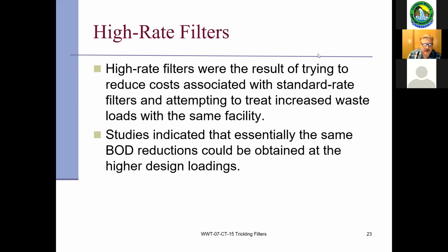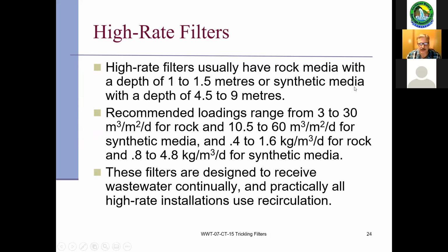So high rate filters, we talked quite a bit about those already. I just want to make mention that the media with rock is 1 to 1.5 meters, and with synthetics it is 4.5 to 9 meters. So why would a high rate filter with rock media have such a difference in meter depth?